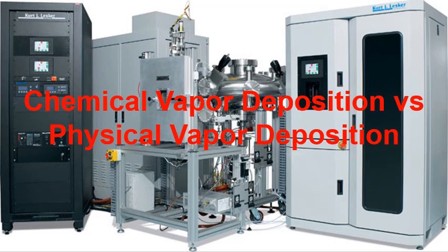So basically, in simple words, in physical vapor deposition process, you deposit the same type of material on the surface of the substrate by evaporating material through electron beam evaporation or thermal evaporation or through sputtering. Whereas in case of chemical vapor deposition process, you deposit a thin film on the surface of the substrate by transporting a precursor in a form of a liquid or a gas onto a surface of a substrate externally, and when it is transported on the surface of the substrate, the precursor material gets reacted chemically and which results in a thin film.